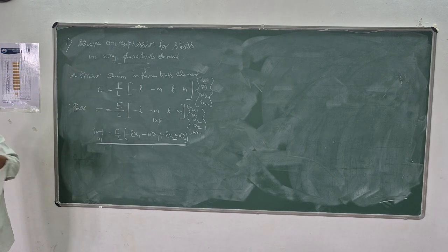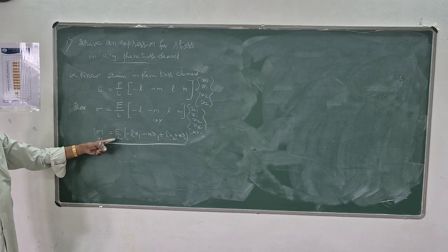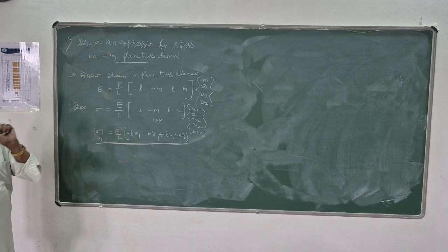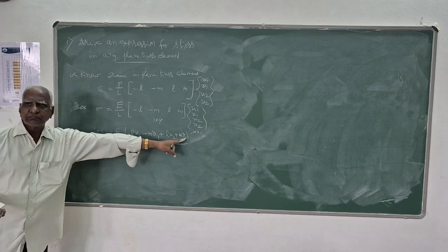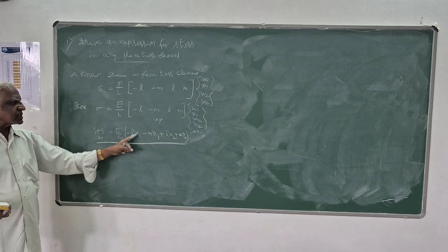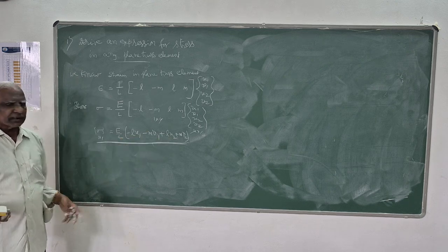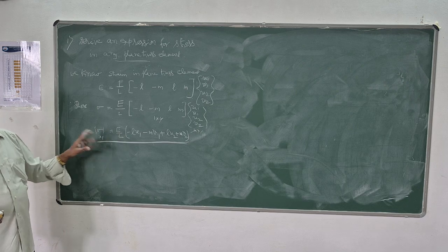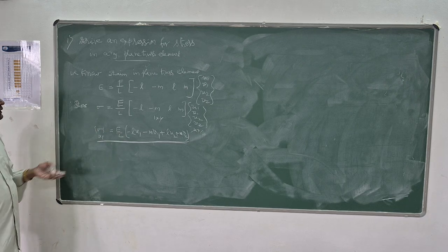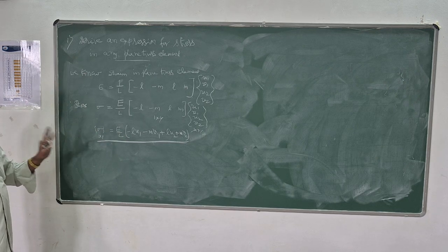After getting the nodal displacements, you can find the stress in that element by just knowing the nodal displacements and multiplying those nodal displacements by the respective direction cosines. Then E by L automatically gives you the stress. That is about that. Very simple step.